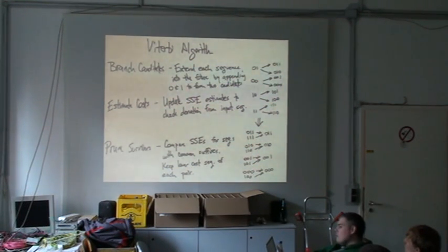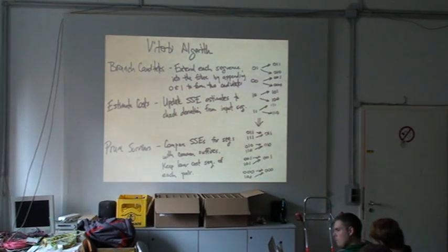Second step is cost estimation. So in the second step, you're going to take each of the candidates, run it through the decoder, and look at the corresponding decoder outputs for the candidate input. And you're going to check the cost. You're going to look at the difference between the output associated with your hypothetical input and what you actually received. These are called costs. And you're going to estimate the cost associated with each of your candidate sequences.